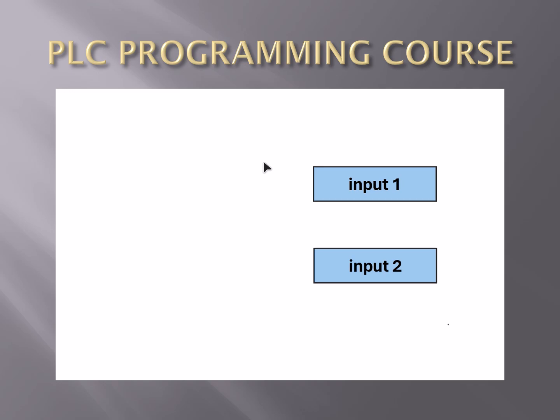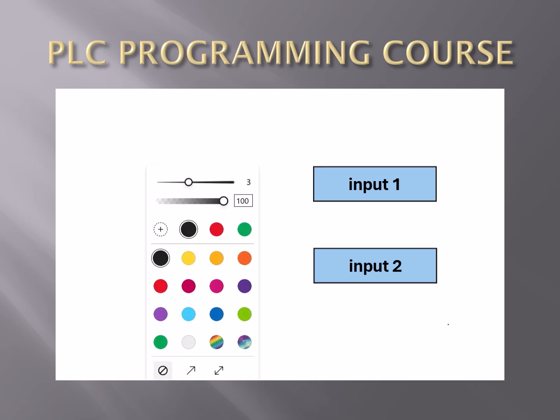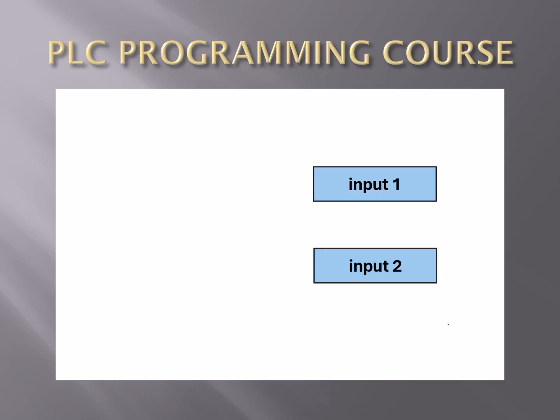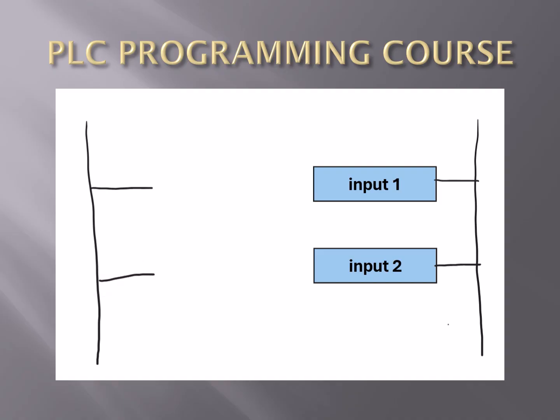So here we're going to try and diagram for you what a syncing and sourcing looks like. Here I'm putting in a common. This is the common for the inputs. This would be a connection on your common of your module. This is your incoming power or your common connection for your field device. I'm going to insert a normally open push button.